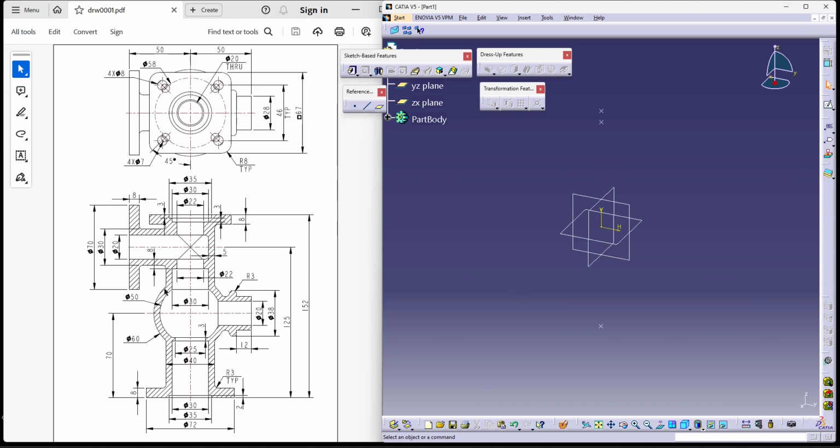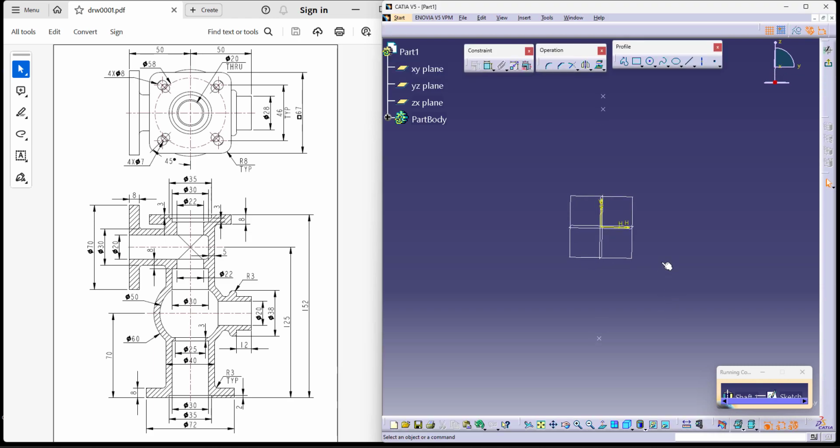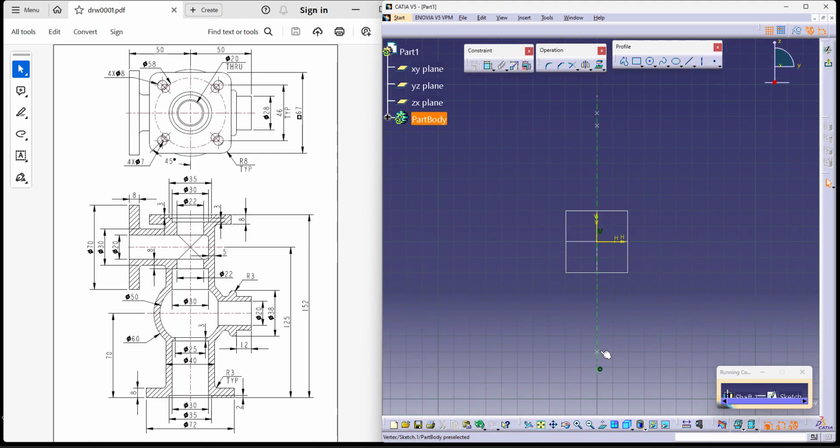Now let us begin making this by using a shaft. The only command you can use to make these kinds of features is shaft. So you can use the shaft directly. You can make the sketch prior to the command or inside the command, whichever you are flexible with. Let us select the axis. I am randomly taking the axis, crossing these two. Now, we do know all my references. This is the first reference and this is the second reference. So we can use them instead of repeating the 70 and 120 over and over again. So I am taking these two as my references at the moment.